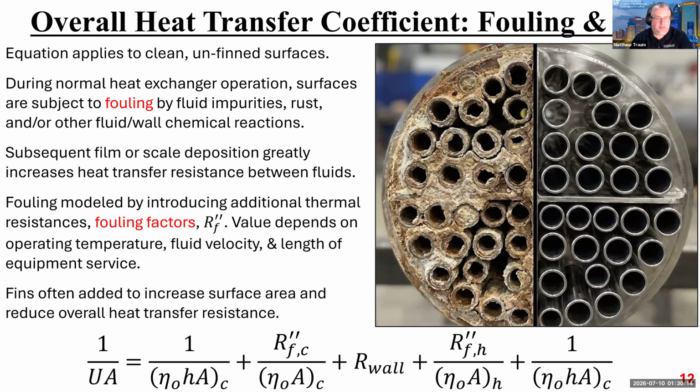Sometimes the inner wall of the tubes, if you've got a solvent carrying liquid running through the inner tubes. But these surfaces basically tend to rust, right? And or be affected by some sort of chemical reaction that then builds up this layer of scale, right? Which then induces its own separate heat transfer resistance, which reduces the overall effectiveness of the heat exchanger, right?